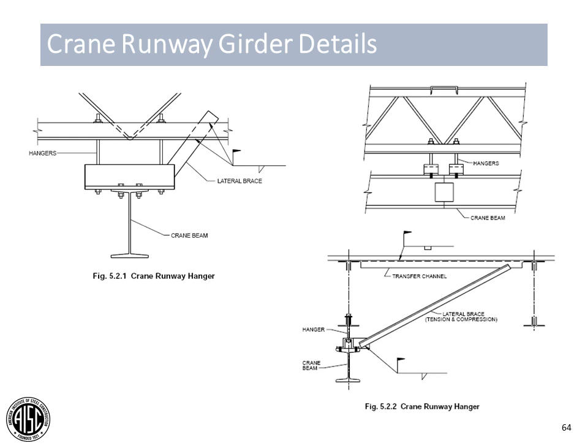Here's a typical runway hanger on the top left here. We've got hanger rods supported through a joist bottom chord. We've also got lateral support provided. You can see how if you have a force applied at this bottom flange, you're definitely going to be introducing a substantial amount of torsion on that system.